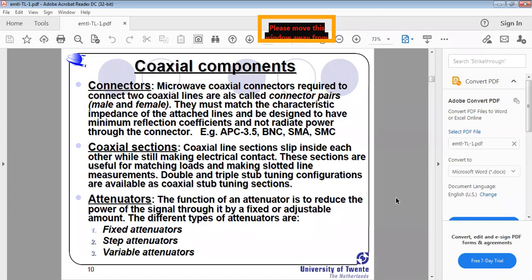Internally it is connected in parallel, not series, and whenever the parallel value increases, the resistance decreases. When two 10 ohm resistors are connected in series, the total is 20 ohms. When two 10 ohm resistors are connected in parallel, the net resistance is 5 ohms. Whenever the parallel connections increase, the net resistance decreases.